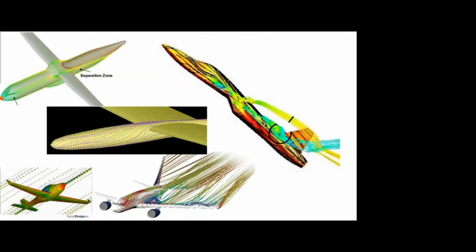You can see the disturbed flow, how it flows on the tail. Okay, so the disturbed flow disturbs both the main wing flow and also the tail wing flow. But compared to the main wing, the tail wing will experience a lot of disturbance. Okay, here also you can see the flow is somehow attached up to this, but from here onwards it is separating. So the fully separated flow affects the tail wing. So compared to the main wing, the tail will experience a lot of drag. That is a lot of disturbance compared to the main wing.